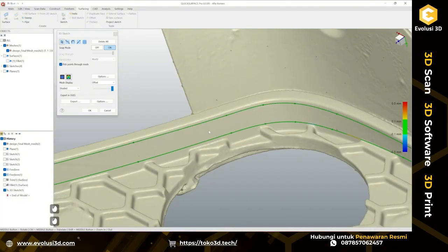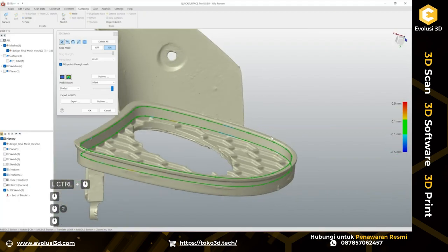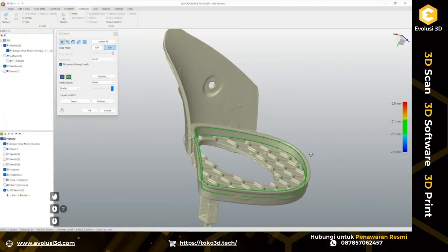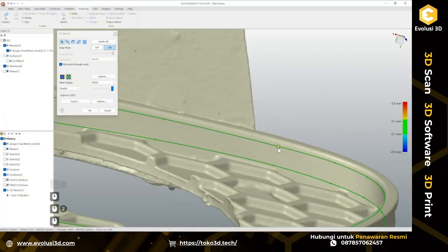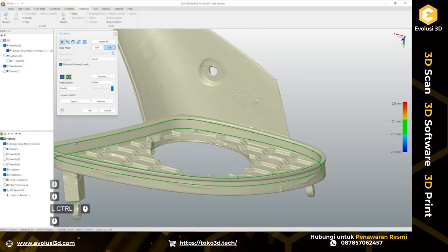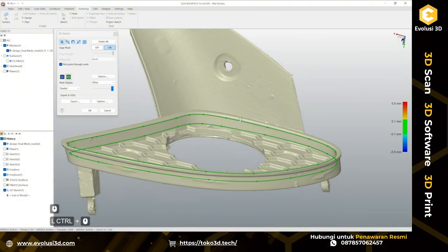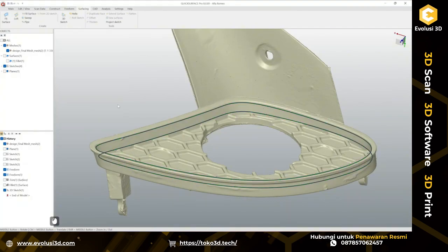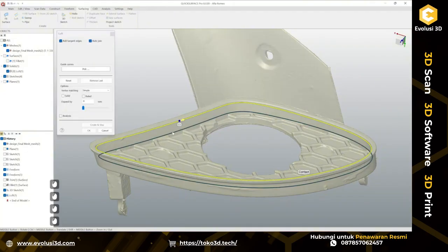And of course, we can reposition some points here and there, or introduce new extra points. For the beginning, I would suggest you play around with existing points to have a nicer and smoother surface overall. Because the more points we have, the more these 3D curves will adapt to your scan data, and sometimes that's not what we want. Basically, we want to use the least possible amount of points that we can manage to produce good deviation, and that will give us the most smooth result possible.